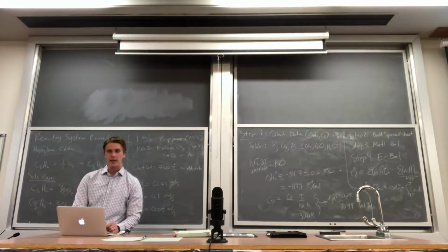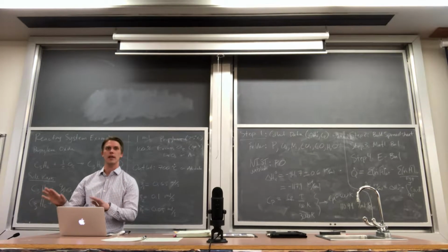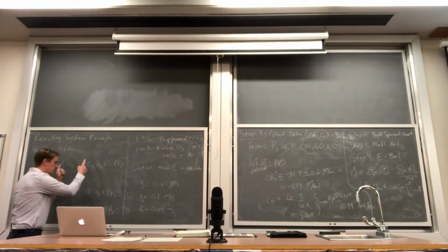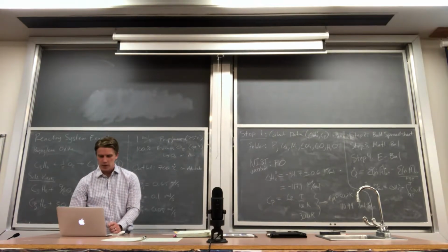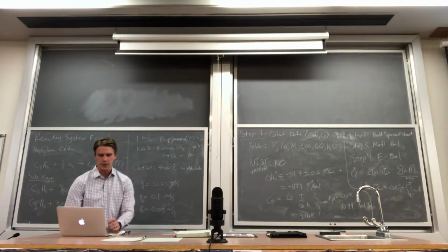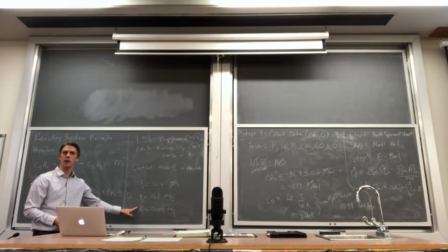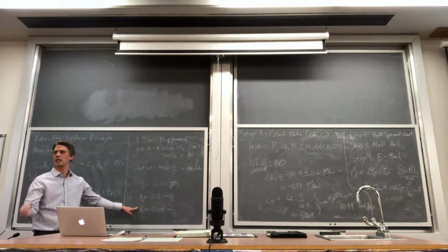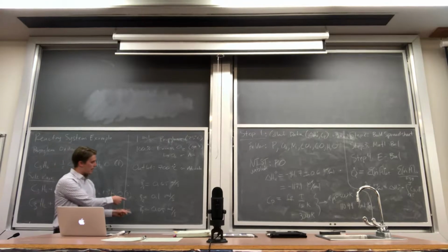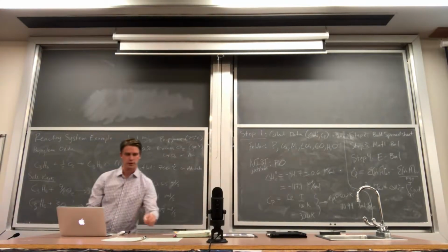Next. Okay, so that is taking care of all the energy coming into the system. So now I just need to figure out all of the energy going out of the system. To accomplish that, I need to balance my material balance for all of the chemical reactions. So, I have my reaction extents that are based on my design specs. Now this might be given to you on an exam in a different way. You might be given conversion or yield or selectivity. But if you can work your way back to calculating the extent of reaction, that's going to be the easiest way to implement the solution. Overall, I would say, if you had a choice.